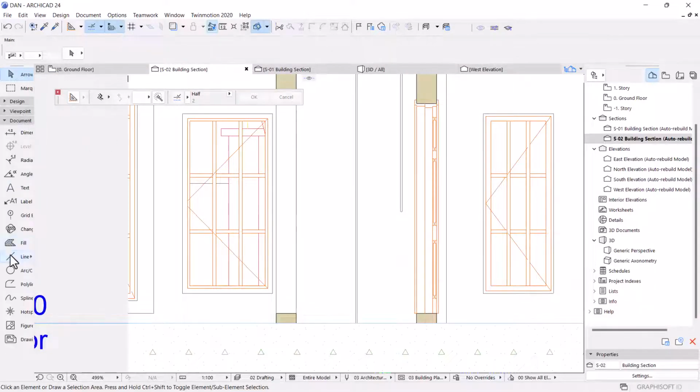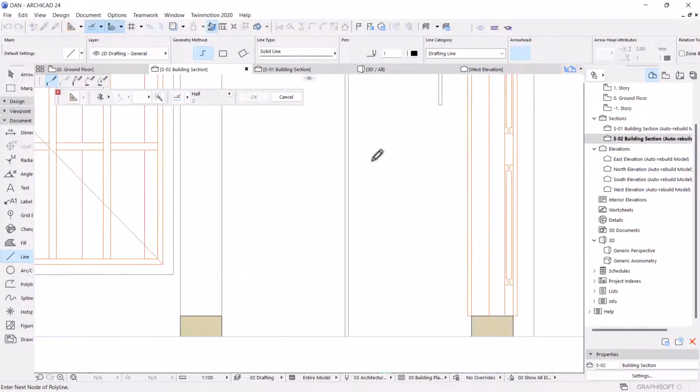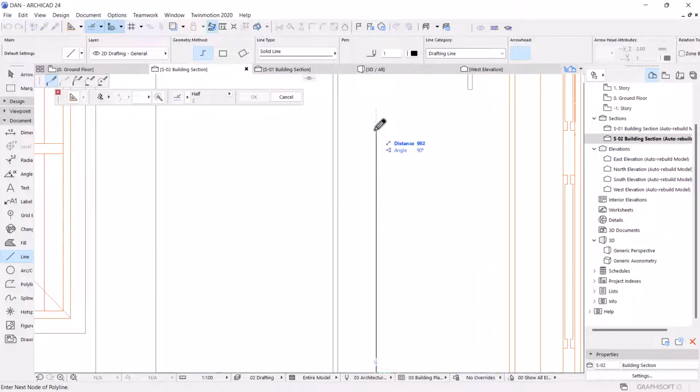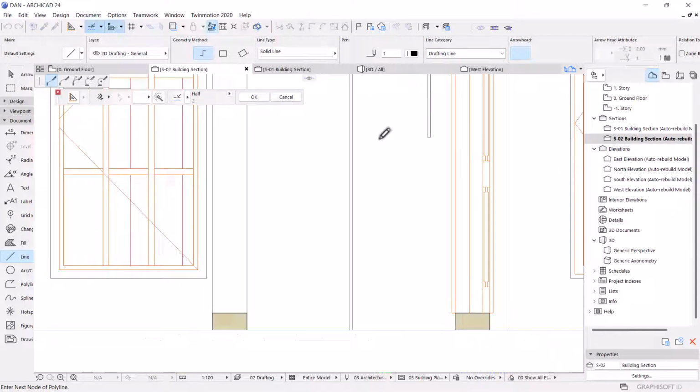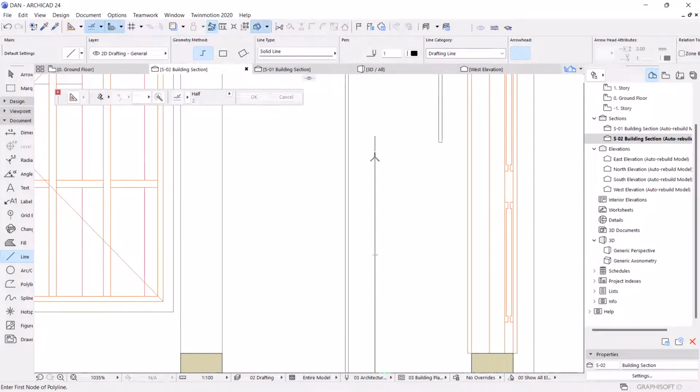So we want to know where our mirror should be from the ground. When we place the hand wash, it will be somewhere around 900 or 950. Sometimes it can go to 1000, but mostly around 950 mm from the ground. So let's have our mirror from 1150, because I might want to have some water taps on the wall. Below the mirror we have maybe 1 or 2 water taps.